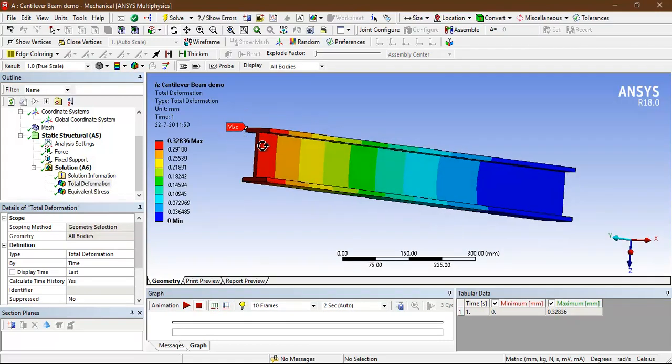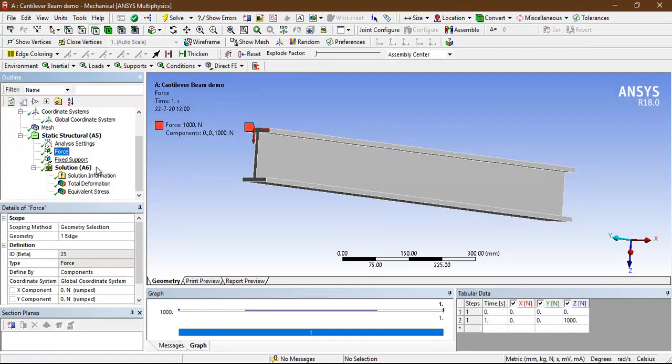Okay, so here also the same result. There's no change, but changes do occur when you are giving a finer mesh. So when you are giving a finer mesh and your structure is so complicated, for example usage of nuts and bolts, you use multiple steps of loading, not a single step of loading. See, on the force criteria, directly in 1 second from 0 to 1000 Newton it went, but in the real case it may not be.